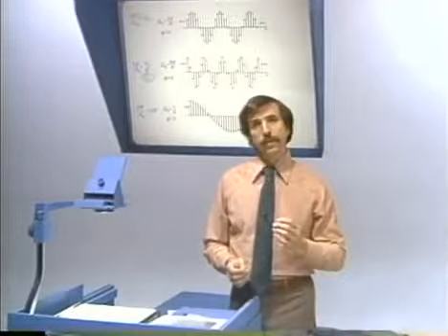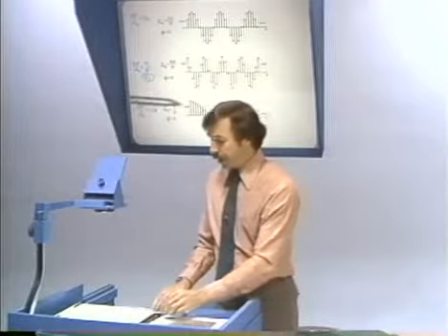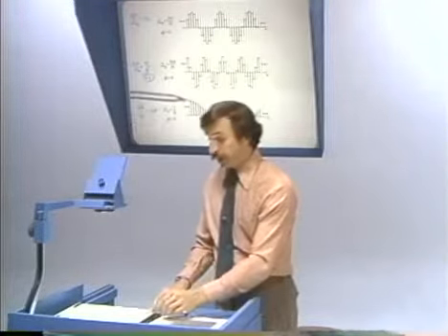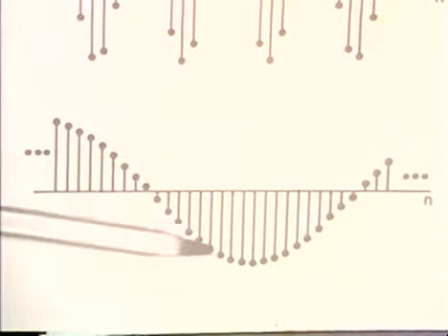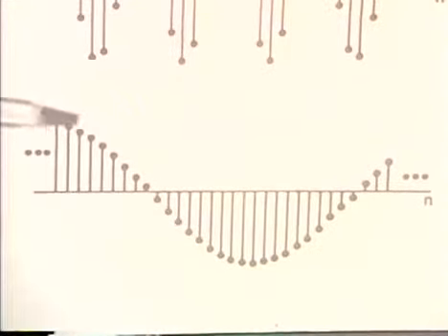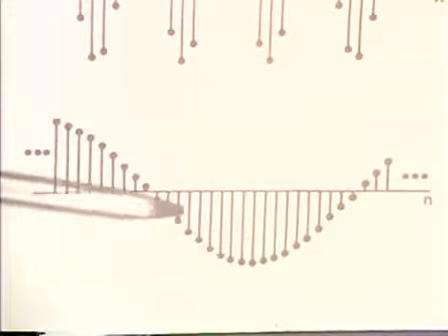So in fact, what that says is that if you look at this sinusoidal signal, it's not periodic at all, even though you might fool yourself into thinking it is simply because the envelope looks periodic. Namely, the continuous time equivalent of this is periodic. The discrete time sequence is not.